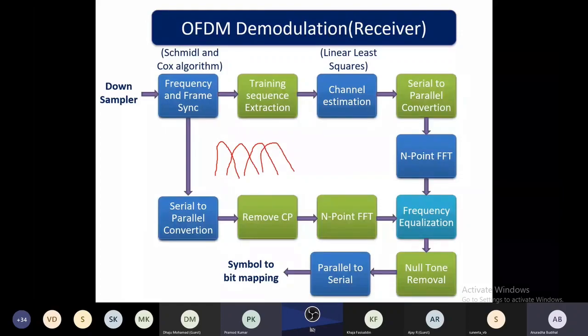This happens because whenever we are working with a USRP, there might be a chance that the local oscillator inside the USRP, if we fix it for 1 gigahertz, will give out 1.1 gigahertz instead of 1. This 0.1 gigahertz difference will impact OFDM more, because all the subcarriers are tightly packed. Even a small mismatch between the carrier signals, and the decoding might not happen.